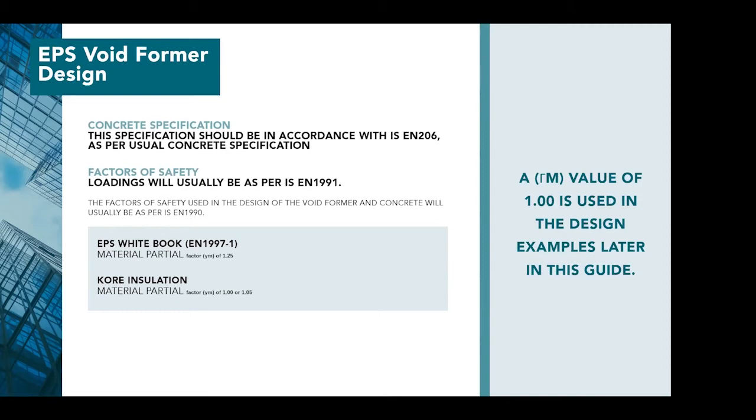Factors of safety are something else that we need to be aware of. Loadings will be as per EN 1991. The factors of safety used for the void former and concrete will usually be as per EN 1990. This standard gives different factors for different combinations.